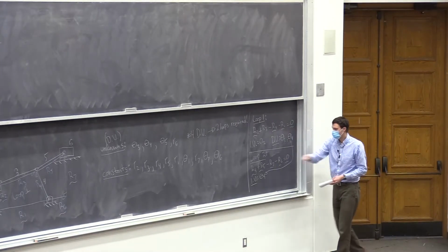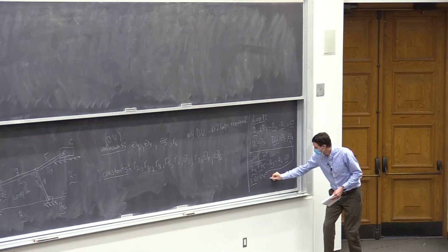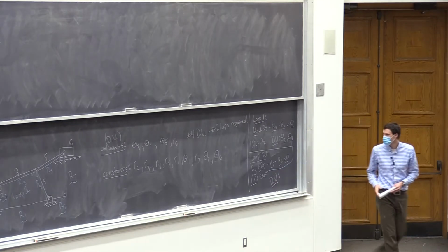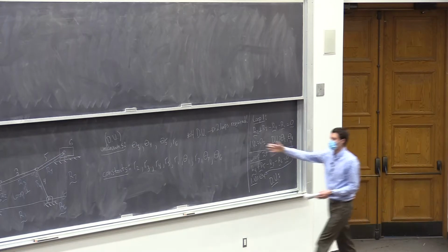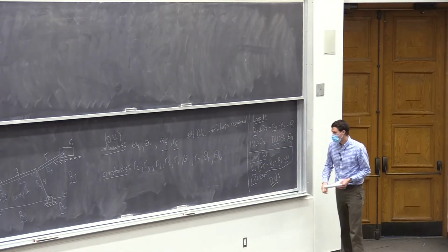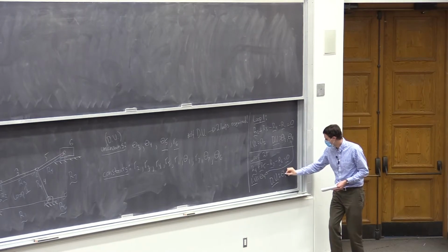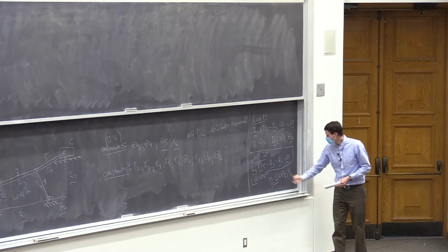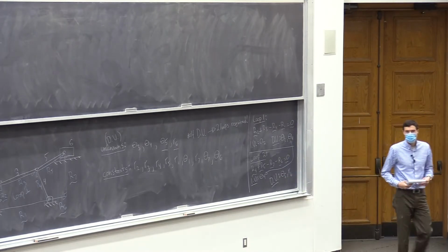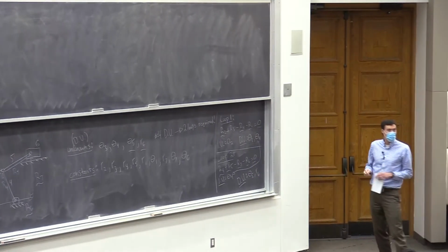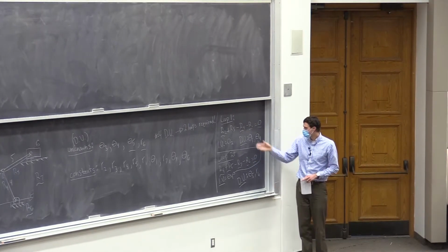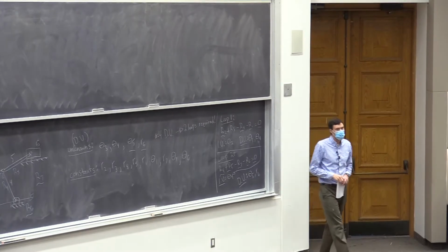First, we'll solve loop 1, plug it into loop 2. And the outputs now are dependent variables. We can look here at our unknowns. It has 5 and it has 6 in it, right? So theta 5 and R6. So we'll have two equations there, and we can solve for these two unknowns. So in total, we're going to have 4 equations, 2 from loop 1, 2 equations from loop 2, and we'll be able to solve for all 4 unknowns.